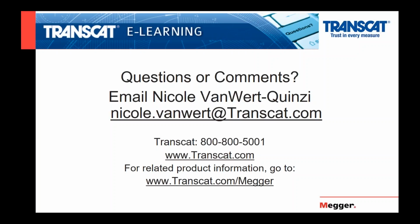It can measure and record AC or DC up to 1,000 volts and up to 6,000 amps. It is actually made in Valley Forge in the USA at our Valley Forge office. With this unit, we have implemented automatic CT recognition and auto connection verification features that only we have. This means you always get good data that you're after, no bad recordings. The unit will actually tell you if you're connected or if your CT is backwards, and allow you to change it and fix it before the recording starts.